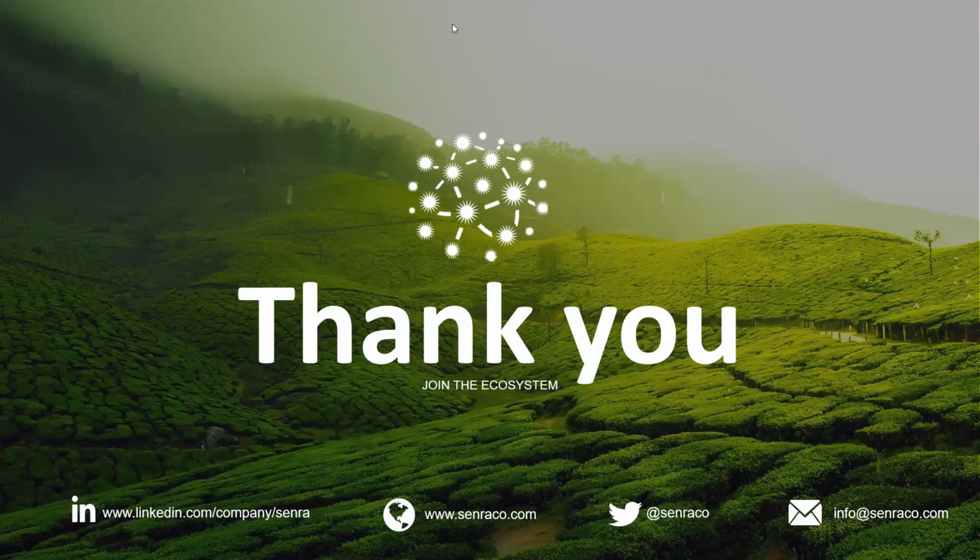Why is the PSR less at some places? The question is why some places are offering a high PSR and some places are offering a low PSR. Guys, note that when your signals are transmitted from the same position on Earth, every time you send a packet you will see a different RSSI because the path loss changes heavily. Mathematically, it's just a Gaussian random variable with a mean and sigma. What that means is that if you have a path loss of 150 dB, it is not necessarily going to be 150 dB all the time, but it's going to vary from, say, 140 to 160. So that is a Gaussian random variable.